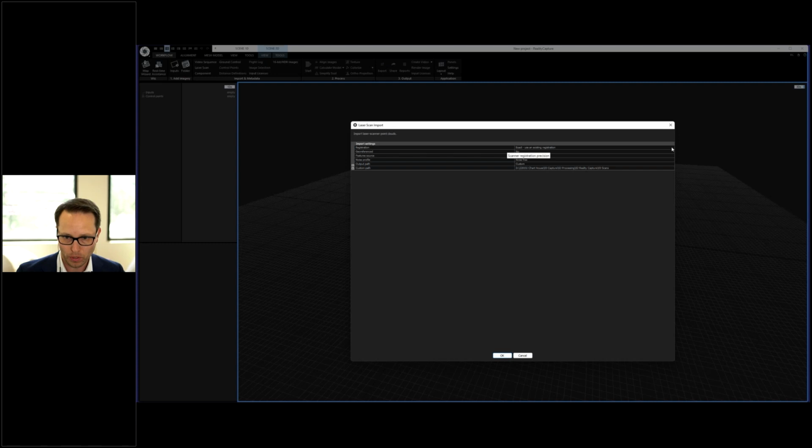And since these are registered, we're going to use the same registration, the exact same registration, because we don't want things to be realigned. Are these geo-referenced? These ones in particular, no. These are color scans. And then if you're using a P20, you have a noise profile for the P20. If not, just set it to noise free.